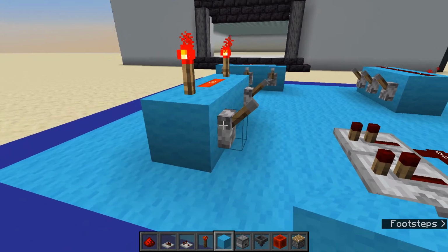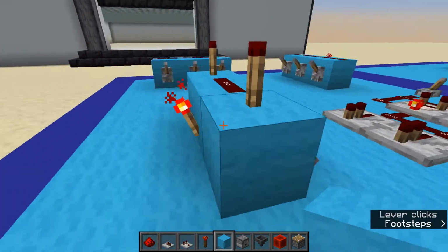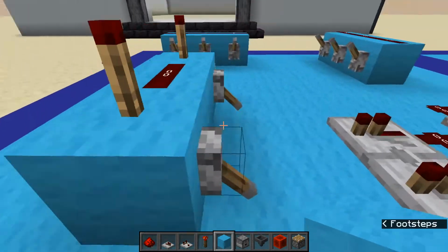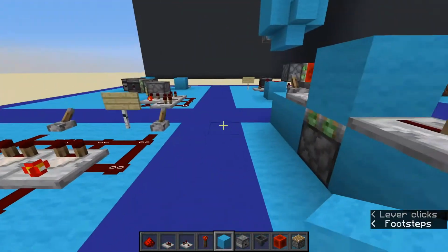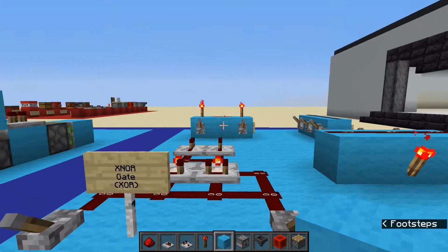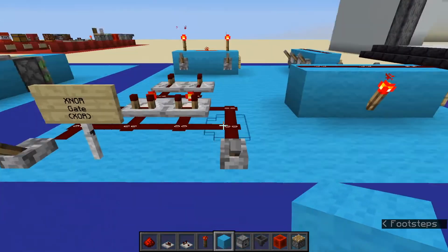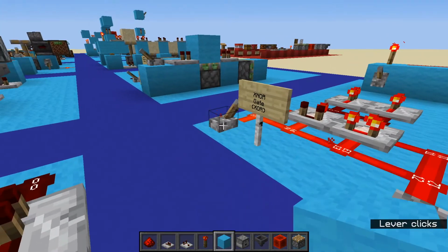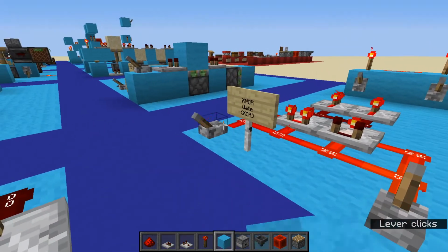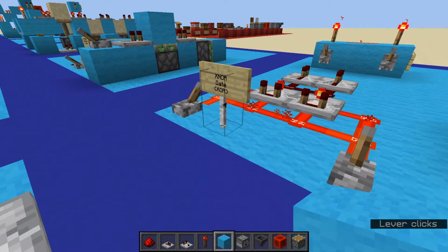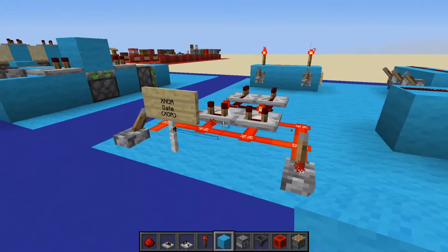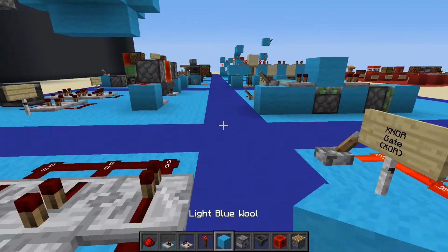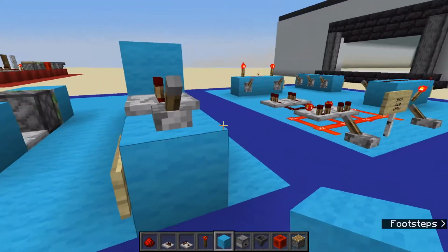Then we do have an AND gate. Only if both of those are activated, we do get a signal. Otherwise, not. And that's basically something similar to this one. Here we do have an XOR gate. If this or this is switched on, we get a signal, but if both aren't switched on, we do not get a signal, because that's an XOR gate or XNOR gate, depending on how you're calling it and what's your source of information.